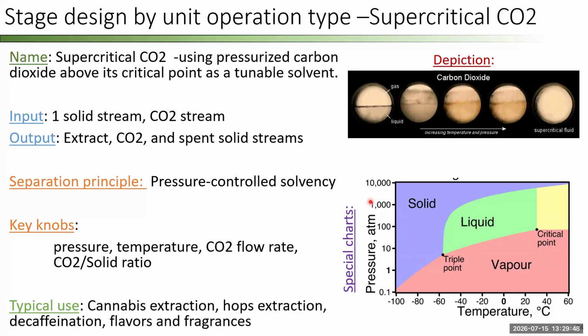Further, it's really important to use things like blast caps, which are pieces of equipment designed to fail at certain pressures, so that if something is going to fail, you want it to fail at that point. Those are generally connected to some sort of emergency ventilation system. Otherwise, not only do you have an explosion, but you have filled a room with CO2, and then you've suffocated all of your employees. We'll spend a little more time talking about safety in one of our later videos.